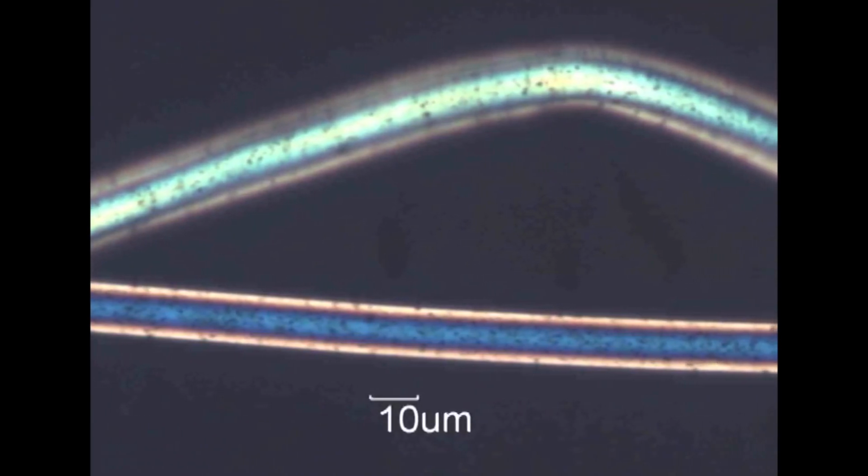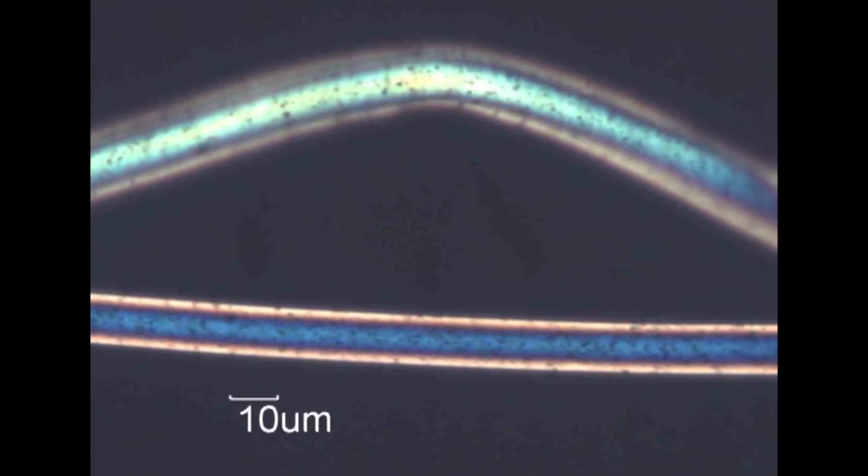And so the luster that is coming out, that shining in the filament, should not be there for all the fabrics, because it is not liked by everybody and for all the purposes. And so these filaments are made dull or semi dull by use of some delustering agent such as titanium dioxide. This titanium dioxide, when it is added in the pigment solution, gets dispersed uniformly, and then it gives us a black spotted effect, and when you see the fiber under a microscope, you will find that there are black spots.